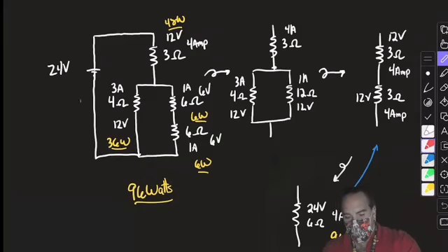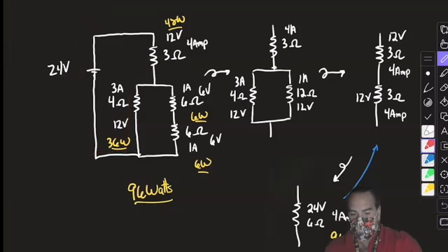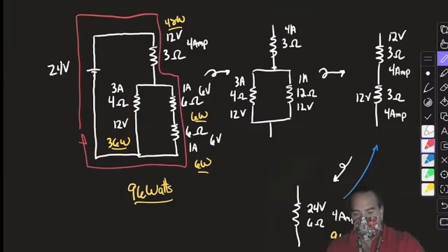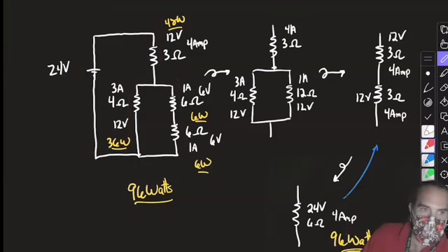On the other hand, if you choose any loop through the circuit, the sum of the voltage drop should be equal to 0. And they are. 12 volts plus 12 volts equals our 24. If I choose maybe this route, I get 12 volts plus 6 volts plus 6 volts, 24 again. So any of our Kirchhoff's rules should be tested and validated here.